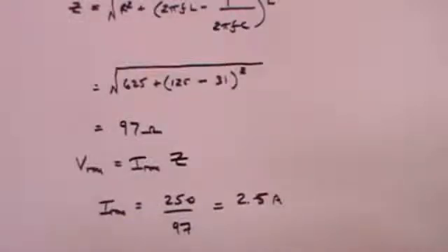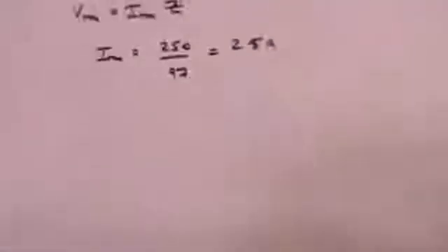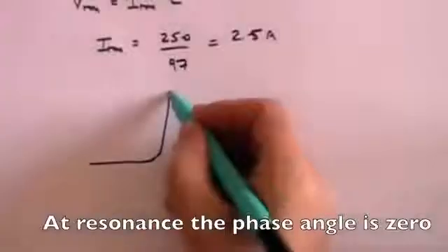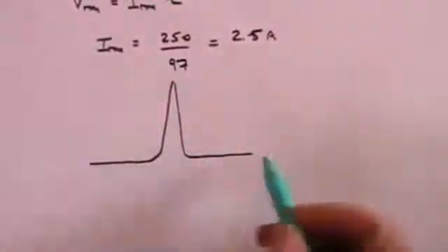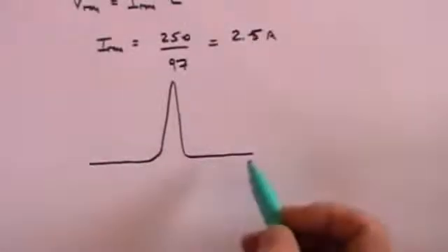So if you were tuning, you'd get quite a lot of interference. The skill with LRC circuits is to adjust the values of L, R and C such that at resonance you get a very high peak of current, but everywhere else you get hardly any current at all.